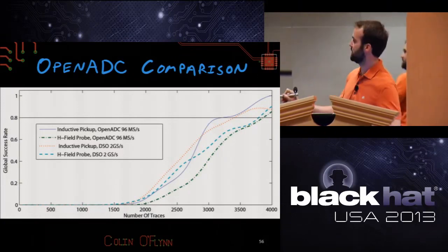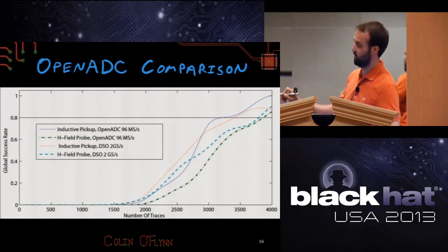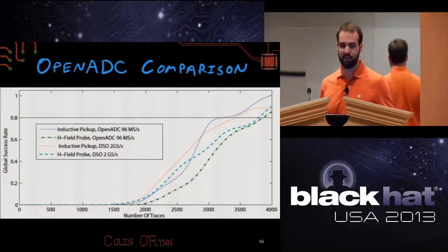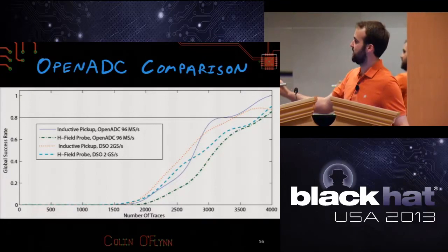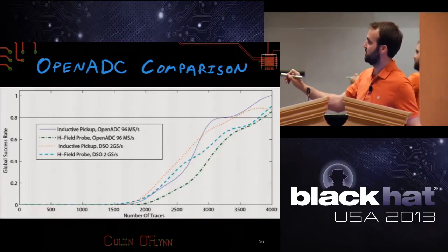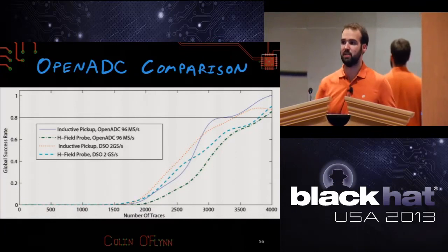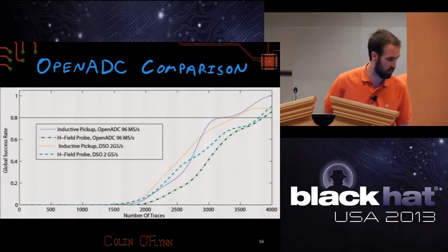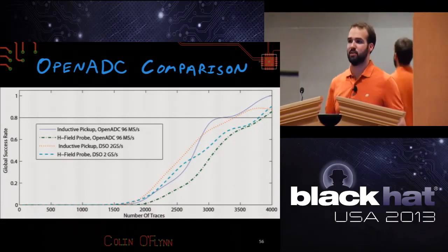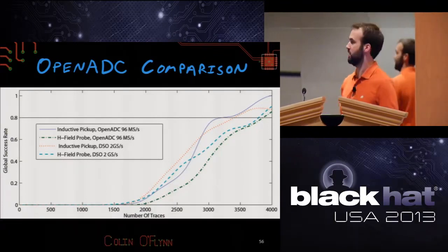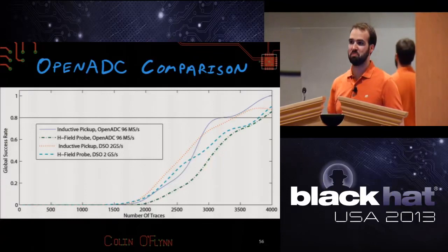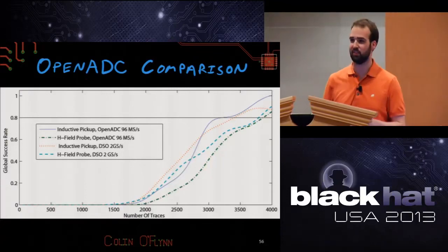It takes more traces. Here it's taking 3,000 traces, and there's a different metric plotted here. This is the success rate. So if I measure the power 3,000 times, 80% of the time I can recover the exact correct key in this hardware implementation, even though it's doing everything at once. So it does in the end work out. Make sense? Other questions? Yep.